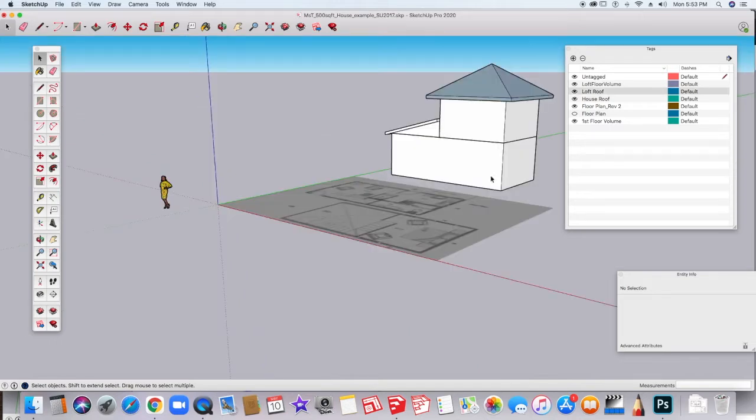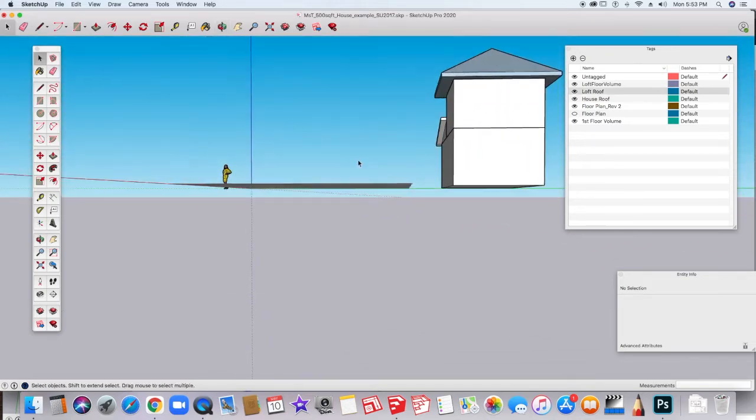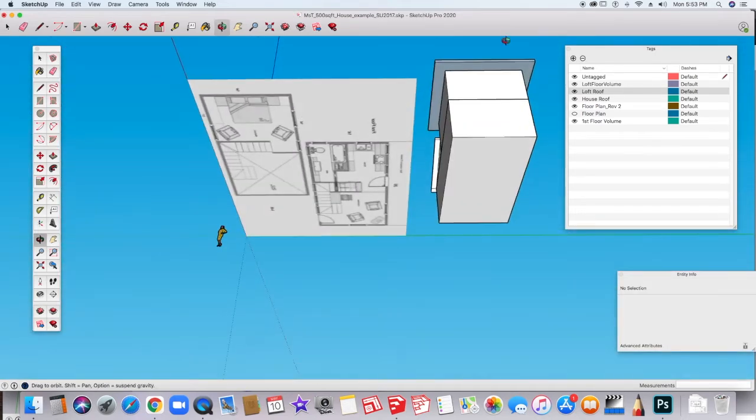What I'm going to do is I'm actually going to redraw the perimeter and use that as the basis of my floor plan. This bottom layer is grouped, and I'm just double checking to make sure it goes into edit mode. So that way I actually know that that's the case. This footprint is exactly the same for both of my floors. I'm going to start by selecting the rectangle tool.